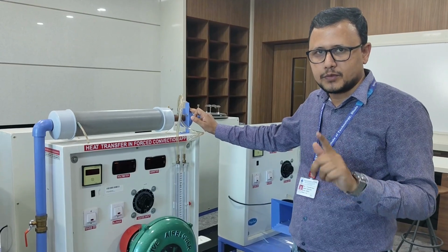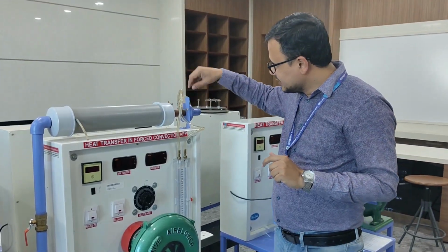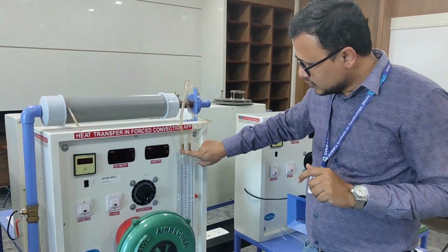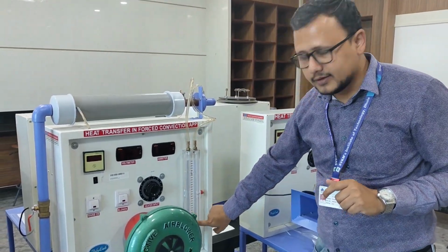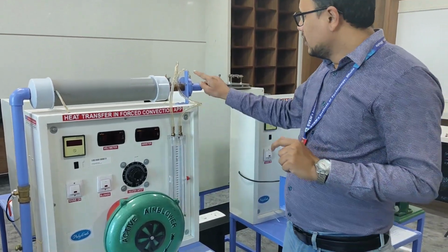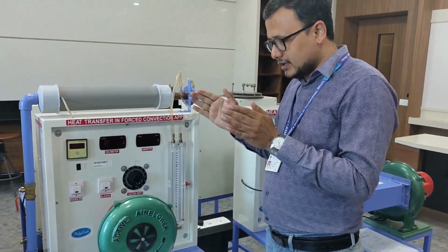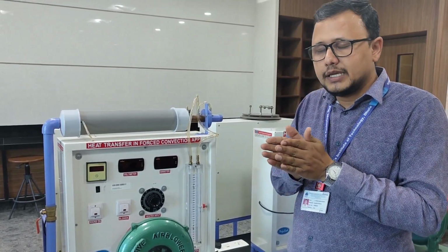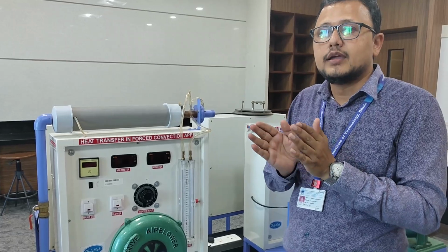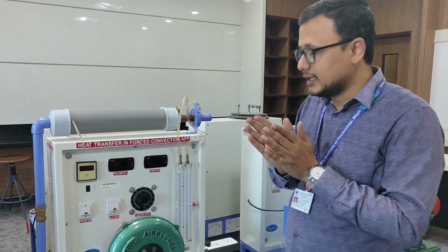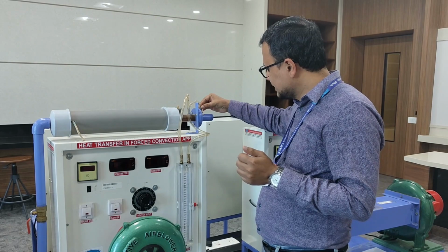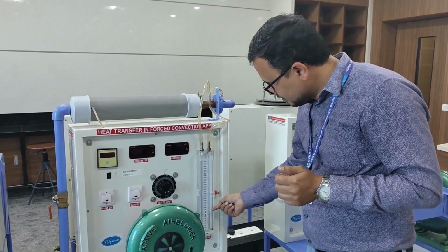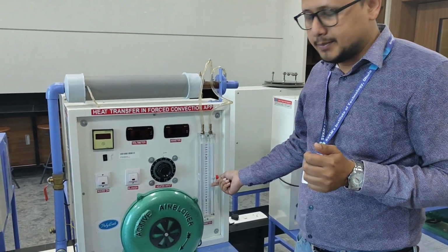In second year, we have understood something called as Bernoulli's equation, and orifice meter is the application of that Bernoulli's equation, which means that at the inlet, which means in the left limb, the pressure will be more. So that's why there will be a depression created in the manometer limb. Once air passes through the orifice meter, there is sudden reduction of the area. Due to sudden reduction, there will be increase in velocity, and that's why reduction in pressure. That reduction in pressure will be measured by the second limb, which means the limb on the right. And that's why there will be rise in the level in this particular limb.